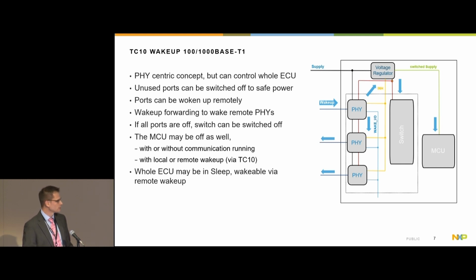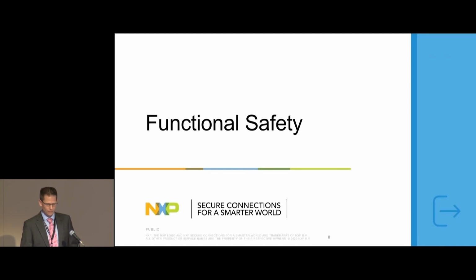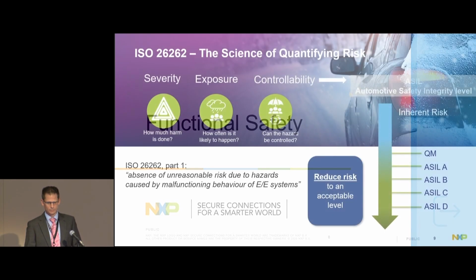The MCU, in principle, is independent from this, but by using the voltage regulator or the wake-up forwarding, you can also handle the sleep and wake-up of the MCU, being controlled by a local wake-up, but also by a remote wake-up. And of course, the complete ECU might be in sleep, and then you use the remote wake-up to wake it up again. So this on sleep and wake-up, and then coming to the functional safety part.